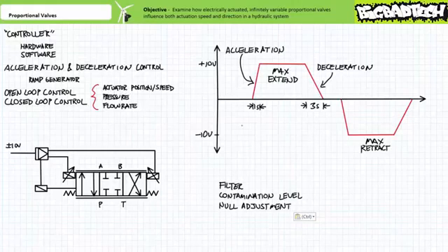We examined proportional valve performance data, specifically flow rate as a function of applied voltage, and discussed deadband, hysteresis, overlap, and line-to-line spools. Additionally, we examine hysteresis compensation via closed-loop control of spool position using the internally generated feedback provided by a spool position transducer known as an LVDT, a linear variable differential transformer. Additionally, we examine acceleration and deceleration control made possible by ramp generators in the controller. And finally, we discuss filtration and fluid requirements and maintenance and service procedures unique to proportional valves.